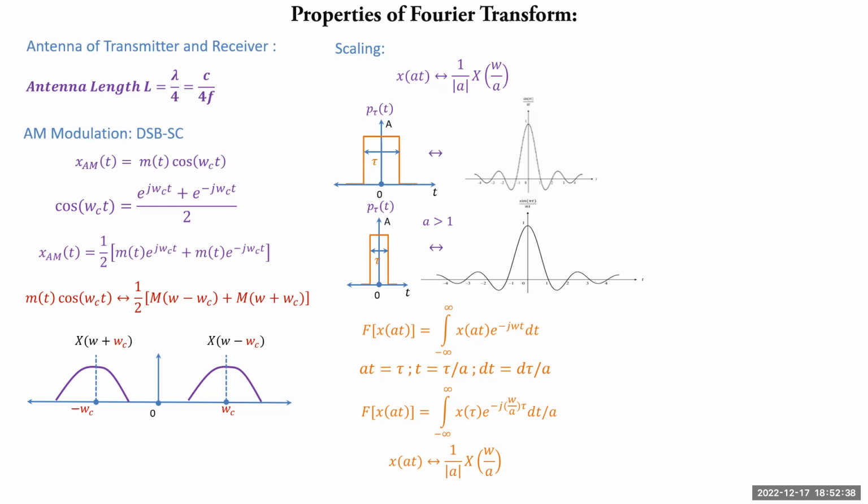We shall see the application of scaling property in a wavelet transform. Wavelet transform itself is another subject. So here we'll see the concept of wavelet transform and how scaling property is used in its definition. So wavelet function is defined as psi of t with parameters a and b is equal to psi of (t minus b) upon a. So here the scaling parameter is used as 1 by a instead of a in order to maintain the mathematical simplicity.